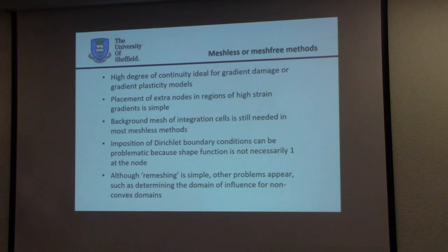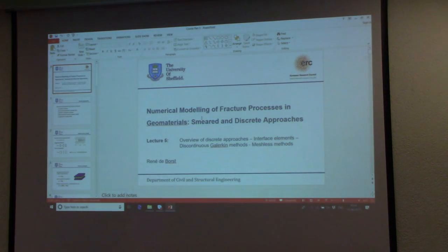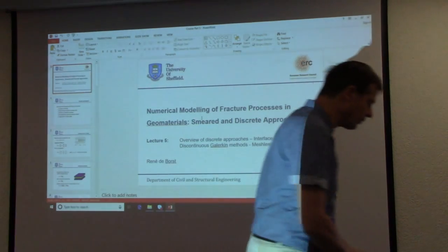But in principle, it's a method that is suitable for discretization of discrete crack propagation, but also for smeared approaches. And although it was originally proposed in the context of discrete crack propagation, linear elastic fracture mechanics, in my mind, smeared approaches like gradient damage combined with meshless methods are the more powerful approach. To the best of my knowledge, it has never been combined with nonlinear fracture mechanics such as cohesive zone models. And I think I would like to, because it connects very well, now directly go on with the extended finite element methods and the isogeometric analysis.